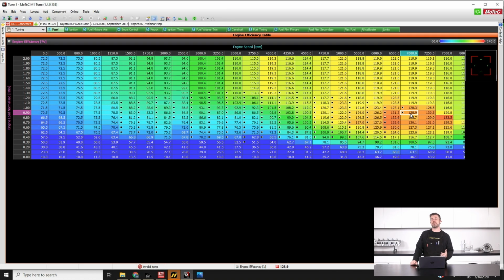We don't have massive changes in altitude here in Queenstown, but I've still been able to test this from around about 250 meters above sea level up to I think around about 1500, and we do find that it gives really, really stable control over the fueling, just again because that barometric air pressure is taken into account with the change in our exhaust back pressure.